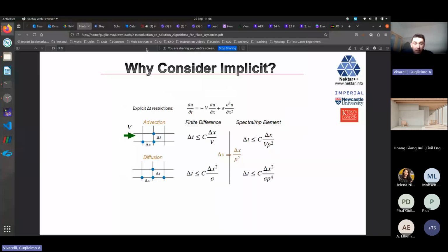So I mentioned the spatial discretization a little bit. So let's talk about why we go directly to implicit for the discontinuous Galerkin incompressible solver. Well, I brought up this slide once again just to remind you that your time step for the high order discretization will scale inversely to the polynomial order, and becomes particularly difficult for the diffusion.